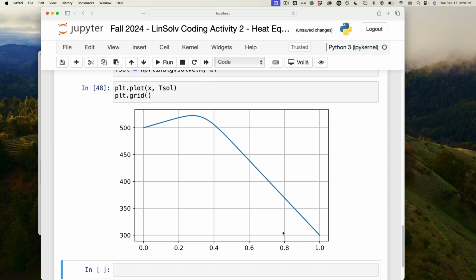Now, indeed, this solution is correct. It was verified with an analytical solution, etc. And I trust this system, so it is giving me the right solution. But in the absence of that, how do you do the sanity check? You ask these questions, like what your colleague asked: is the temperature peaking where the heat source is? Well, it's a little harder to answer without knowing too much heat transfer. But if the temperatures are fixed and the heating is going to cause an increase in temperature, you bet it's going to make that temperature peak exactly there.